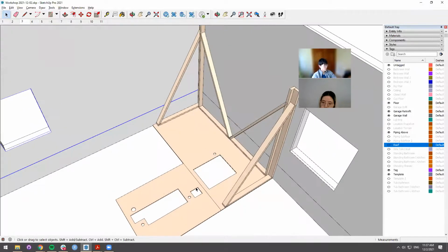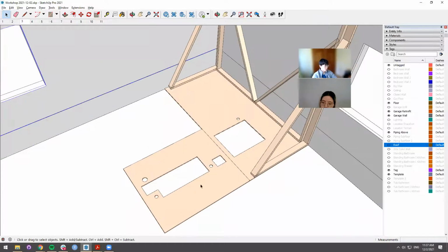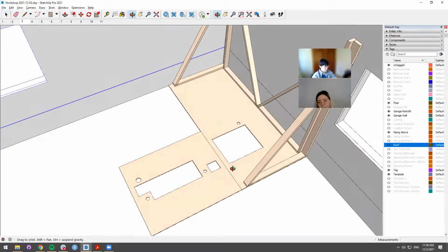But you can see on the ground that there are some holes, circular and square holes. That is related to our thinking around subfloor plumbing. So these holes you can see here are the only penetrations we imagine being necessary for a duo design, which would be a shower drain, a sink drain, and a toilet drain, and then potentially some coming back upwards for vent pipes.